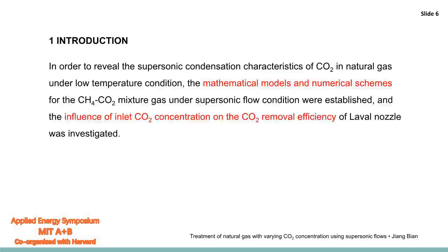So in this paper, in order to review the supersonic condensation characteristics of CO2 in natural gas, we established the mathematical models and numerical schemes for the CH4-CO2 mixture gas and studied the influence of inlet CO2 concentration on the CO2 removal efficiency.